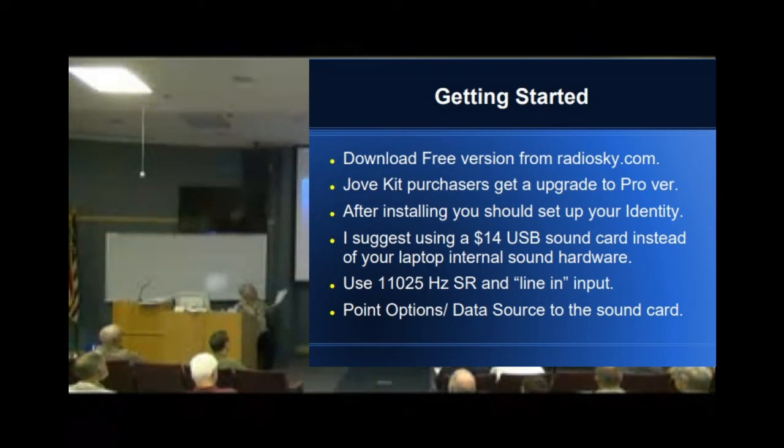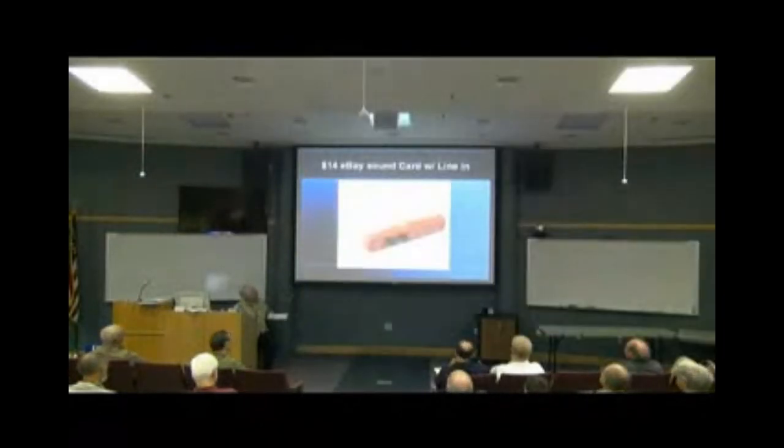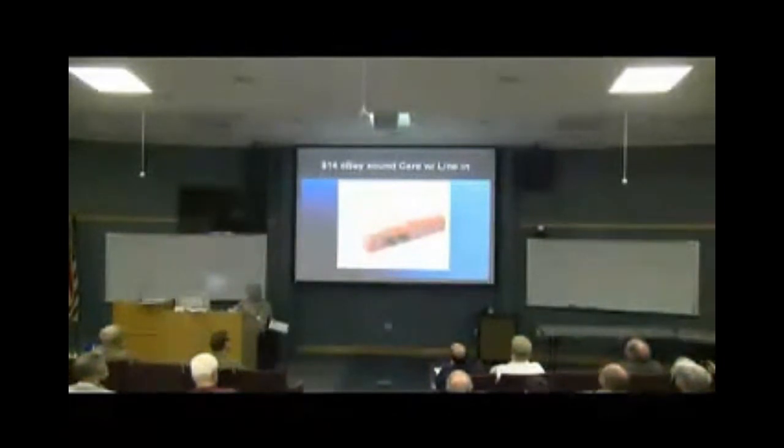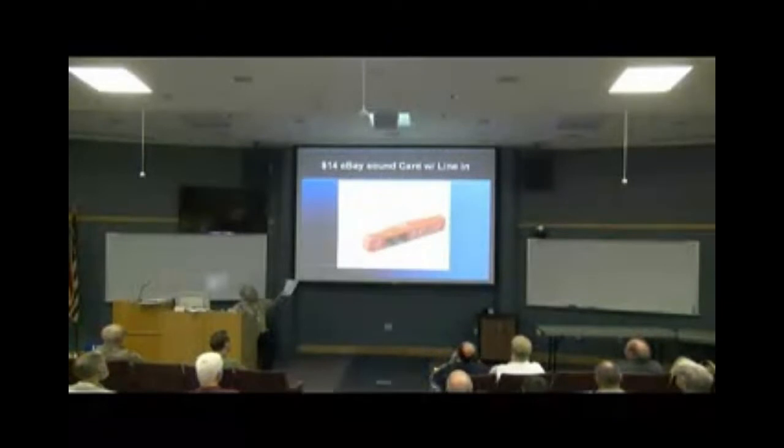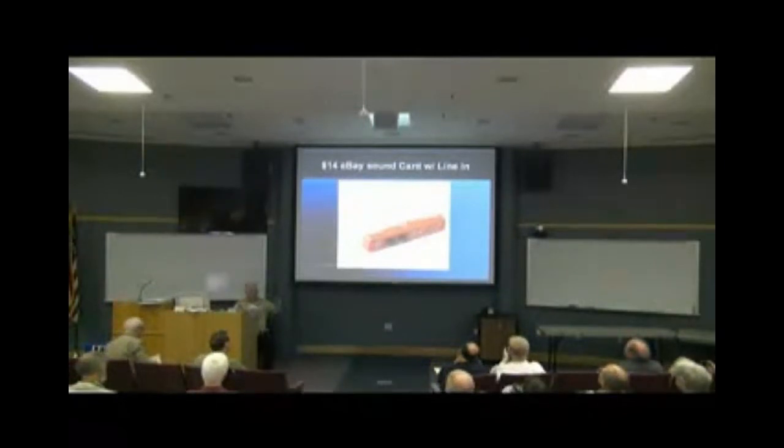So I'm suggesting that people buy a little $14 USB card for that situation. And this is just one I snagged from eBay, but I know that this particular one works. And it has an official line input in there. So you can stick in 2 channels of audio into it, and it won't be messed up by microphone processing in the sound card.